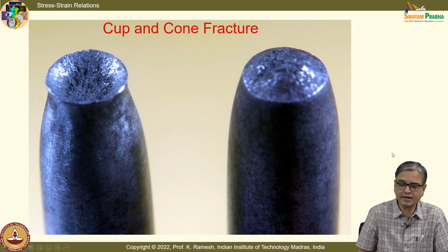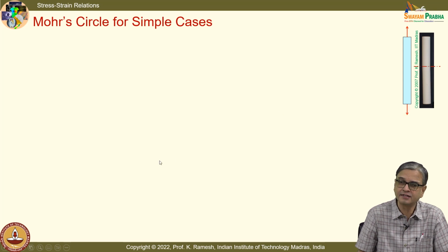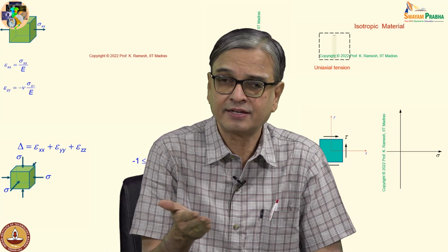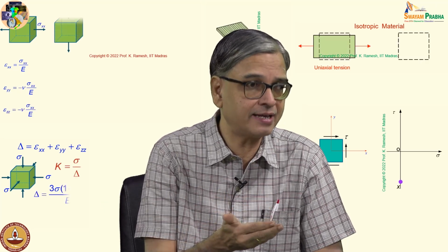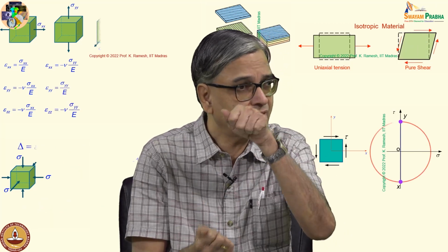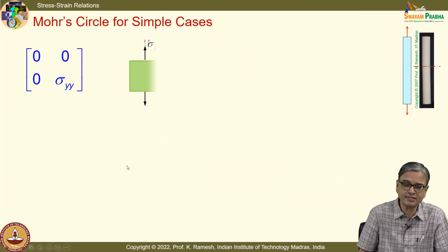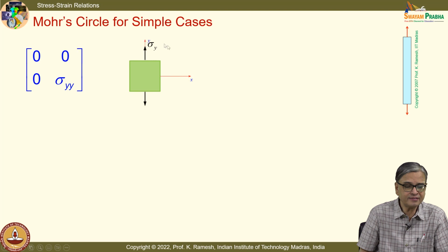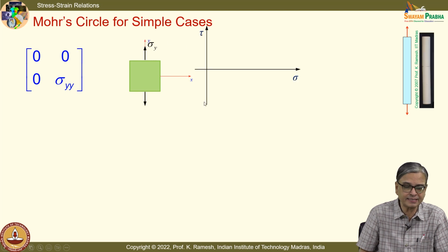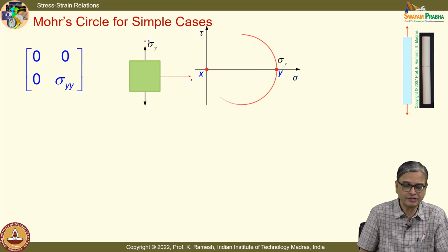And we have also looked at the Mohr circle for a uniaxial loading. We have discussed why a chalk fails like this. We have also seen epoxy, which behaves in a brittle manner. In an actual video I showed that when you pull it, it was getting separated horizontally. Fine. So that reinforces the reason that brittle materials fail by maximum normal stress. That can be a good model for your failure theory.